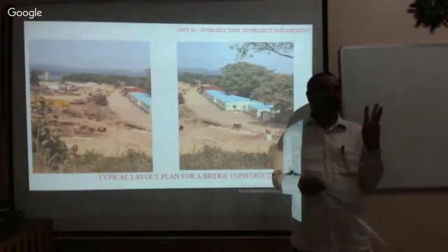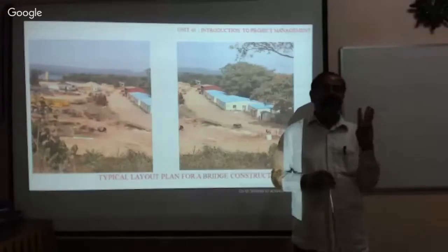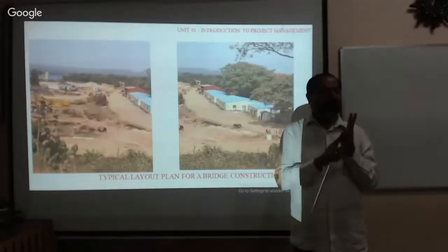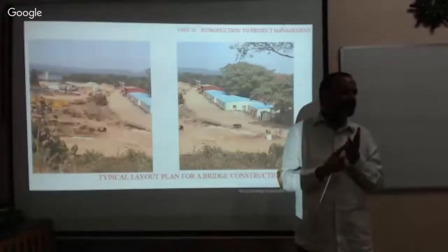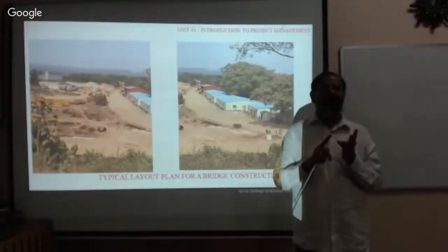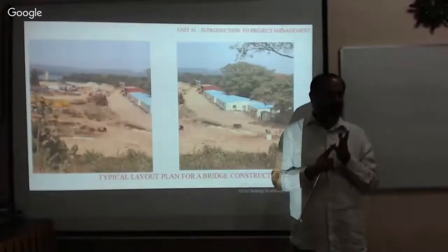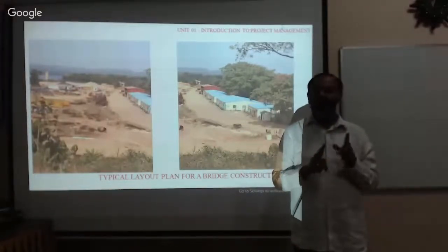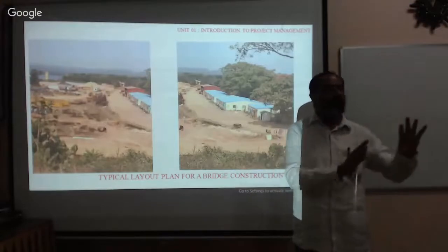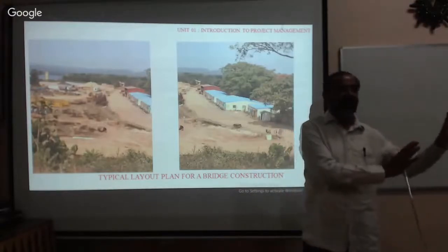The advantages of this job layout. Number one, no disturbance for the different activities. A bar vendor, a shuttering contractor, shuttering workers, the office or supervisor, nobody will be disturbed. Everybody keeps doing their job at different places.